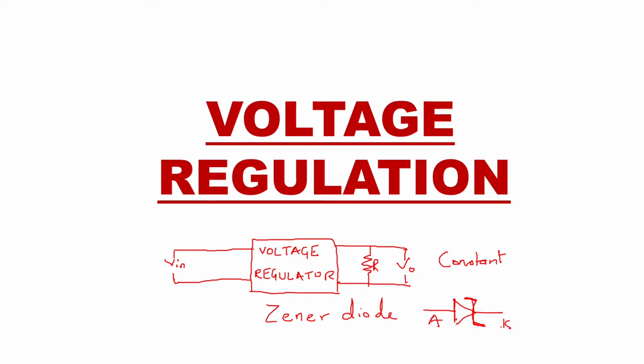But when it comes to electronic appliances and electronic circuits, the circuits require a lower voltage, and that voltage should remain constant. The supply given to a particular circuit should not vary. Otherwise, the components in your circuit will malfunction. The behavior will not be correct, and then you might get wrong results. So the supply you give to your circuit is very important. Here the voltage regulation concept comes in the power supply part, the power supply which you give to your circuits.